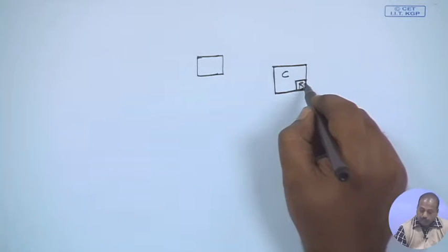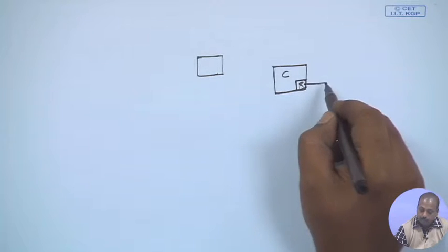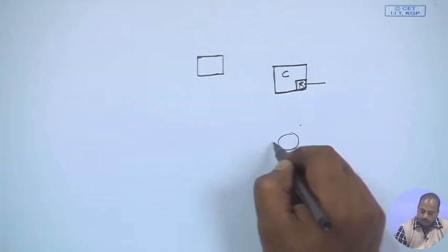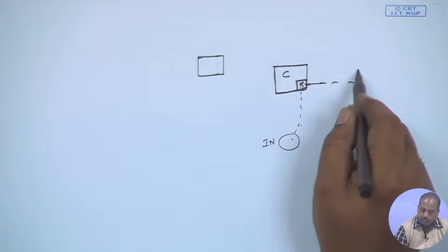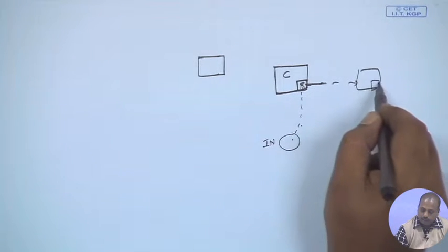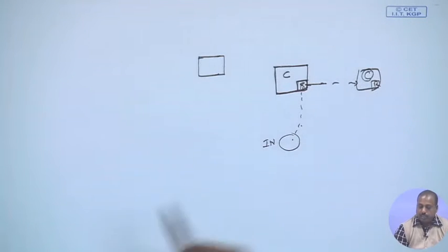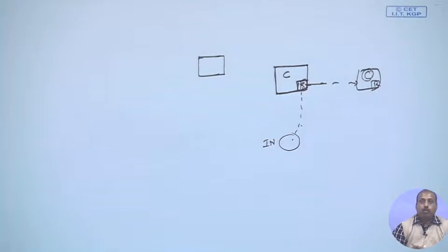But these routers may be taking part in communicating some pattern that is coming from some other core, from the input port or the input core. It may be going through this router to the destination core. So, the router there may be connected, this core is being tested, and these patterns are going like this. So, this router needs to be kept on. As a result this entire tile is kept on.